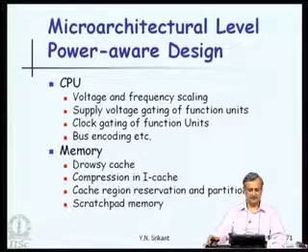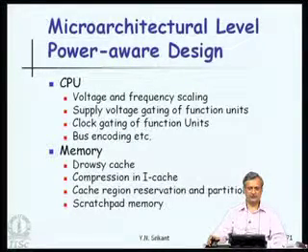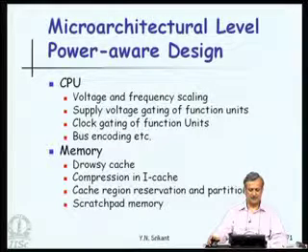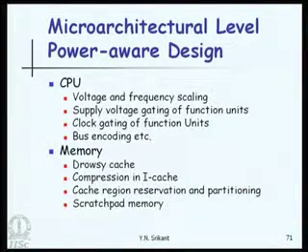It has a facility to switch off power supply to several cache lines which are not active. Compression in the instruction cache is possible to save energy, because if we compress instructions, then the space occupied will be much lesser. So, the access will be faster and less energy consuming. Cache region reservation and partitioning, and scratch pad memory, are some of the techniques which are possible at the microarchitectural level.